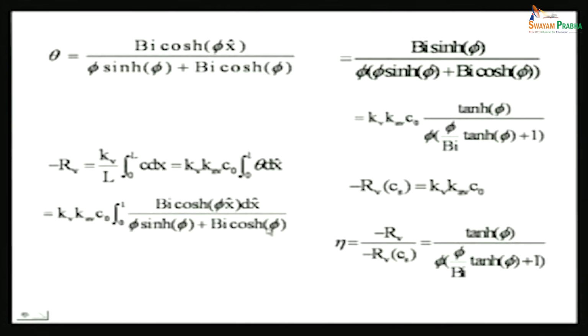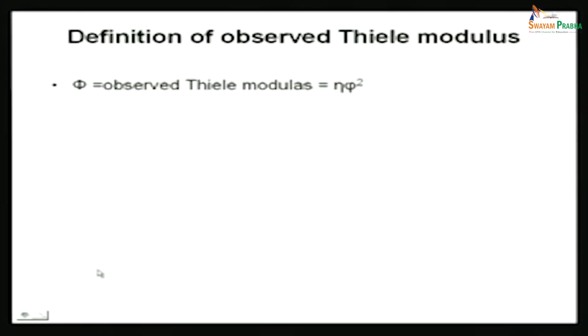What we're going to do in today's lecture is try to obtain a general expression for the effectiveness factor. I told you that when we derived the effectiveness factor for the normal slab, it comes out to be tanh phi over phi, and that this is an expression you could use for different kinds of geometries provided you make certain changes to phi. That is, you define phi in terms of the effective length L. The length L is going to be half the length for a slab, for a sphere it's going to be something else, and for a radius it's going to be something else, and we'll figure out how to do that today. So that's the first thing we'll do today.